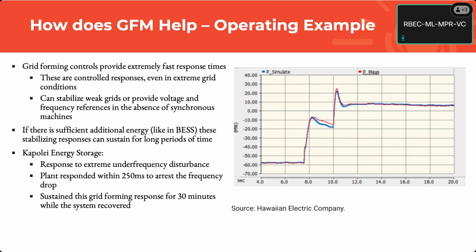Okay, so you can see this can come up and stay up because they can add in essentially grid following controls on top of that to make it give you whatever energy profile you want. So it's current limited, that's true. And sometimes that's a downside. Most of the time, it's offset by the extreme benefit you can get from those controls afterwards.